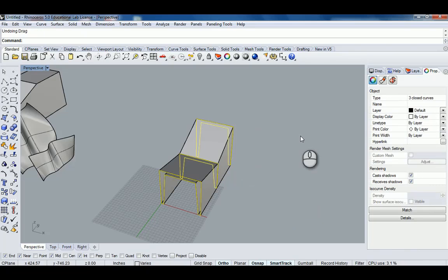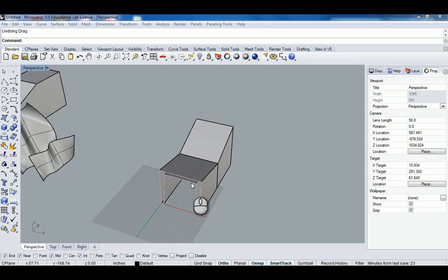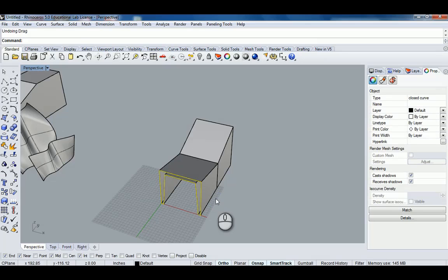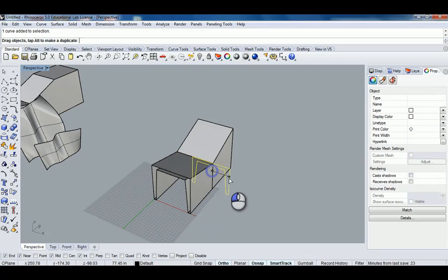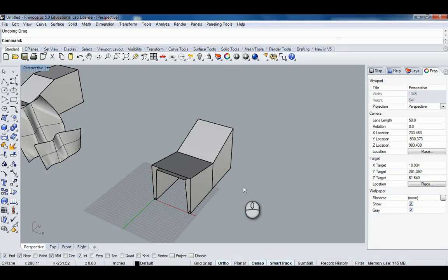So obviously, I think you guys can see the potential in that. Quick updates to a shape, to the location of a shape. If you destroy the integrity of that shape, or you delete a component of that shape, it will break the record history moment, and it won't continue to update it dynamically. And that will be true in Grasshopper as well. If you break certain layers of the input data in Grasshopper, it'll basically give you an error saying, oh, I can't complete the path because I'm now missing data that I thought was there. So if I were to delete this curve, I believe that me moving this around, it's now broken the record history because it's lacking the data points throughout to do the full loft.